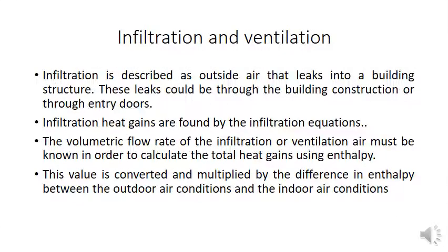Now, apart from solar radiation and electrical appliances, some infiltration and ventilation loads are also considered. Infiltration is nothing but the outside air which may leak into the building structure. It may be due to defects in the construction, or through a porous wall, or maybe through the entry doors and windows. It may be considered by the infiltration equation.